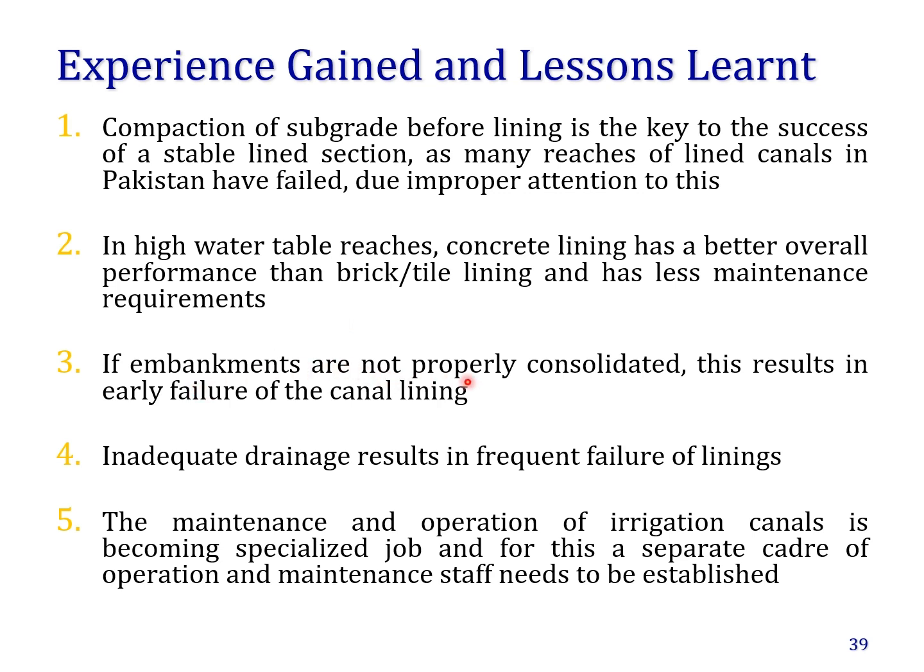If the embankments are not properly consolidated, the result is early failure of the canal lining. Of course, consolidation is very important. Loose soil will cause instability in the canal lining. Inadequate drainage results in frequent failure of the lining.